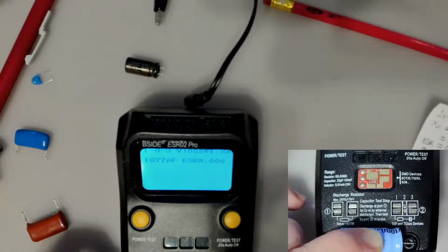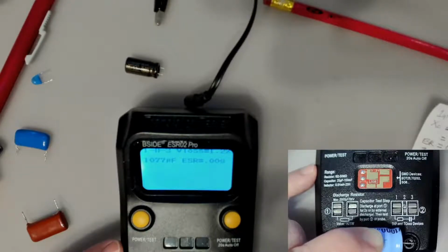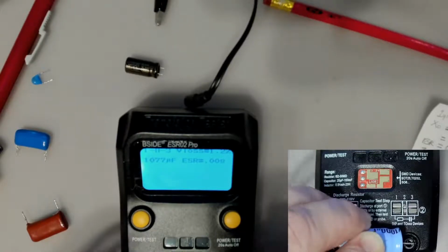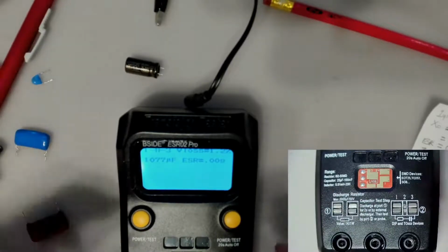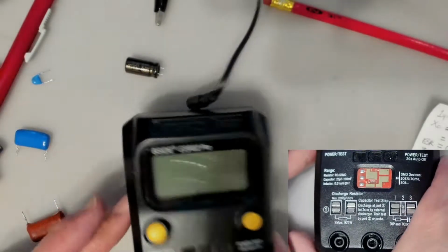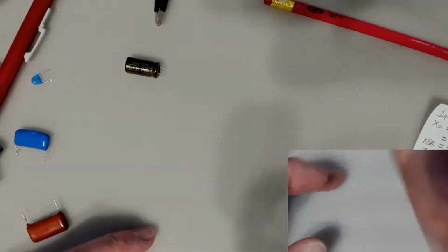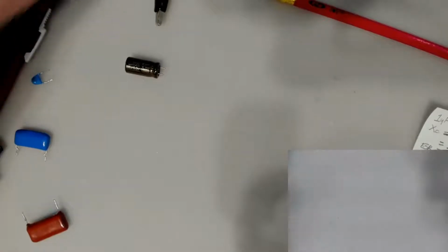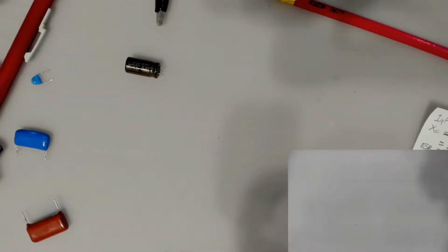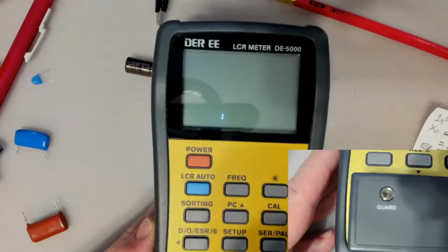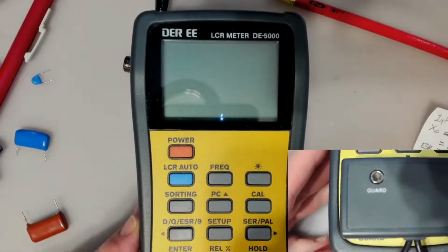Well, it says 1077 microfarads. I guess that's not bad, but it has an ESR of 0.00, which is not all that accurate. We know it's 0.0 something, but not 00. In any case, it kind of works. This is a cheap thing. Let's put that aside and let us have a look at this thing here, which is a proper LCR